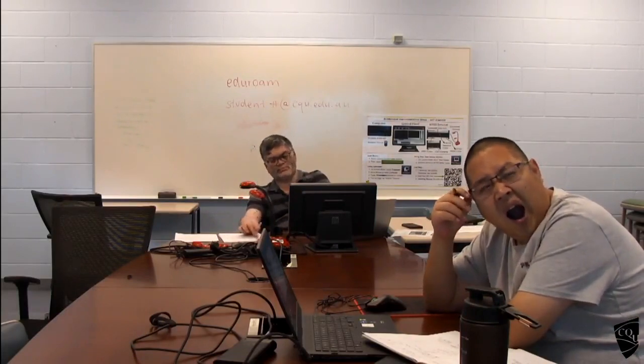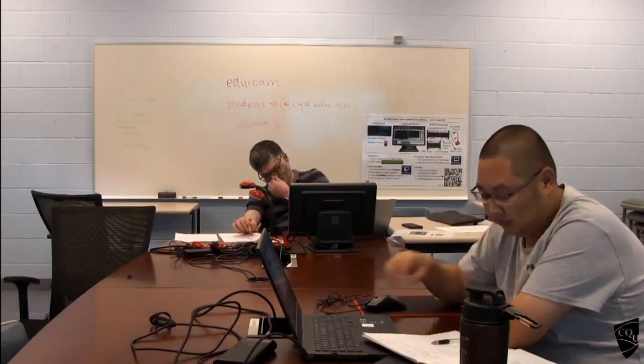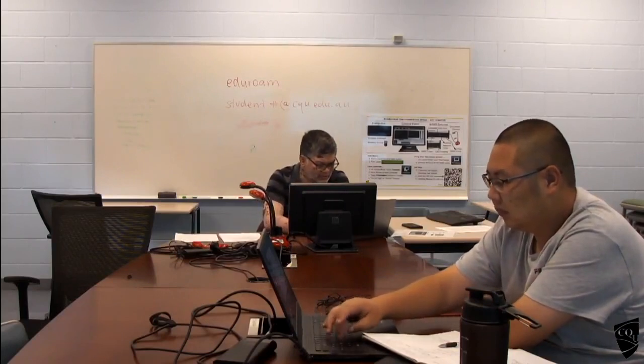For different loading conditions it is different, but I think the tutorial I used the simply supported. So the equation is this one, deflection. So the load, length, EI. I already calculated, but if you look at the relevant standard, they said how to use the equivalent I value. Okay, let's show that one.